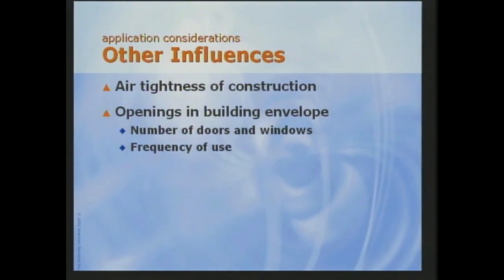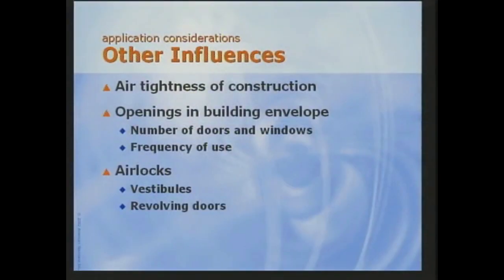The more often the door is open, the more difficult pressure control becomes. Buildings with high door opening frequency, like retail stores, often act leaky regardless of construction. To maintain building pressure and to assure proper operation, it may be better if doors don't connect directly to outside. That's what vestibules, entrance tunnels, and revolving doors are for.